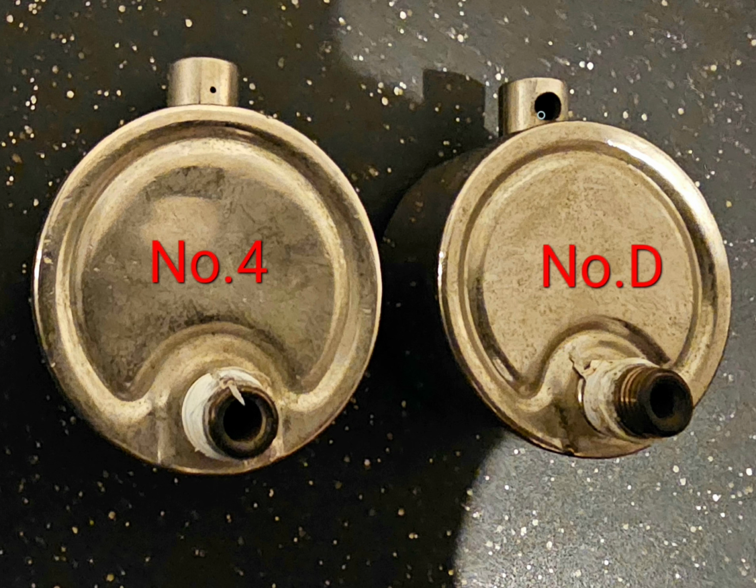Also, the next thing I've noticed about the Gordon's vents, they're very good vents, but in certain cases, they don't all seal the right way when these things heat up. Meaning that the valve can heat up, it'll lock out, but yet you'll still get steam slowly escaping through the outlet, which can be a good or bad thing because you can keep your radiator vented, but depending on how much it's venting, you might be really just losing a lot of water or just stuff that you really don't need happening.